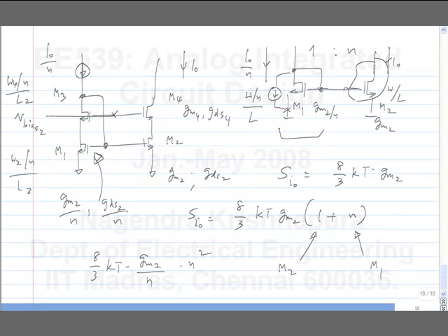The voltage controlled oscillator is biased from this current source. It turns out that it can be very sensitive to the noise here. So there certainly you don't want to multiply up a very small current. You will have to go from a significantly large current to whatever you have. Okay. So that's one part I wanted to discuss here.